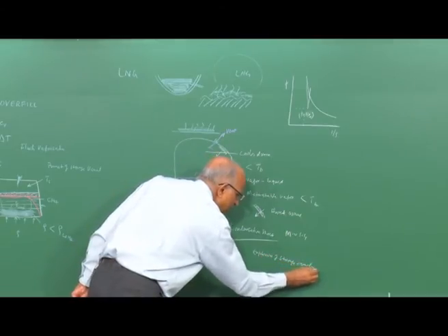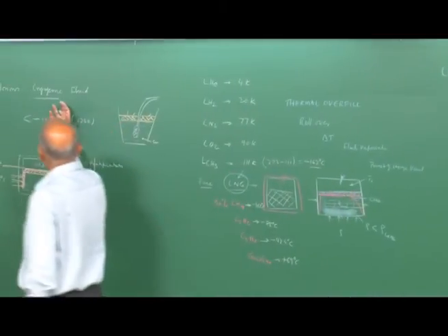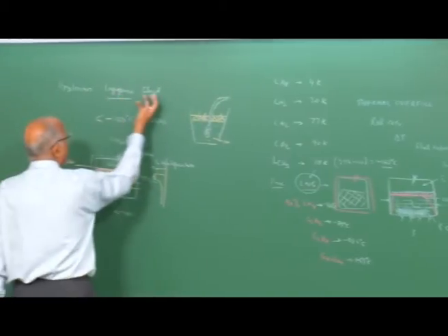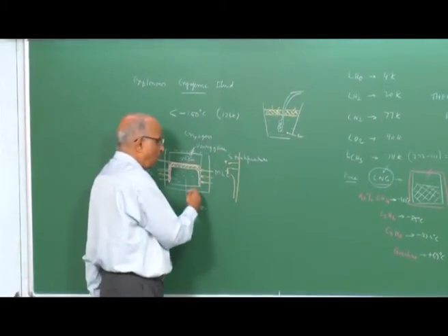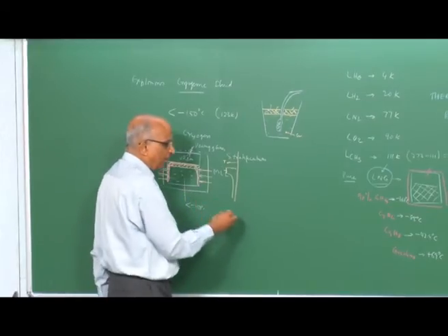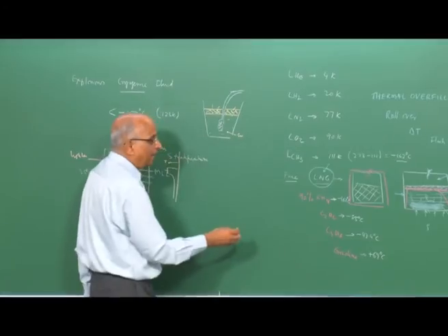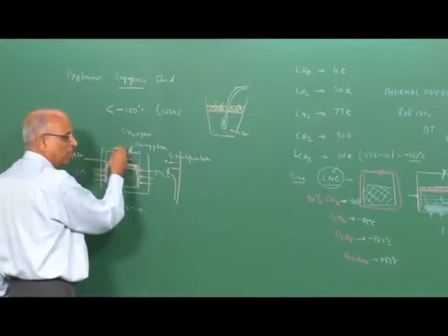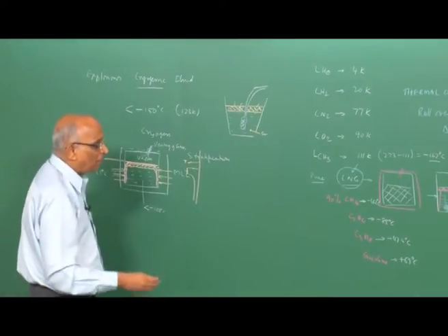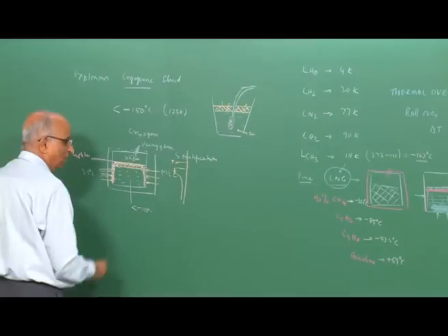Therefore, we can summarize by saying, when we consider explosions of cryogenic liquids in storage vessels, first, there is thermal overfill and rollover associated with different constituents in the cryogen, and secondly, condensation shock could contribute to the explosion. Well, this is about the explosions of cryogenic storage vessels.